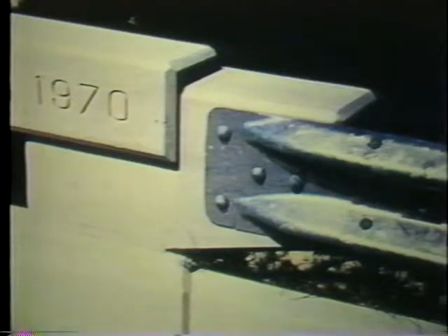The W-beam and end cap connections are correctly installed. All the bolts are in place, and the W-beam is correctly lapped for the approach rail. The concrete parapet wall must be strong enough to transmit the beam loads. The concrete may break if it is not reinforced. And here you see a situation where the concrete did break. The bridge rail must also be structurally sound.